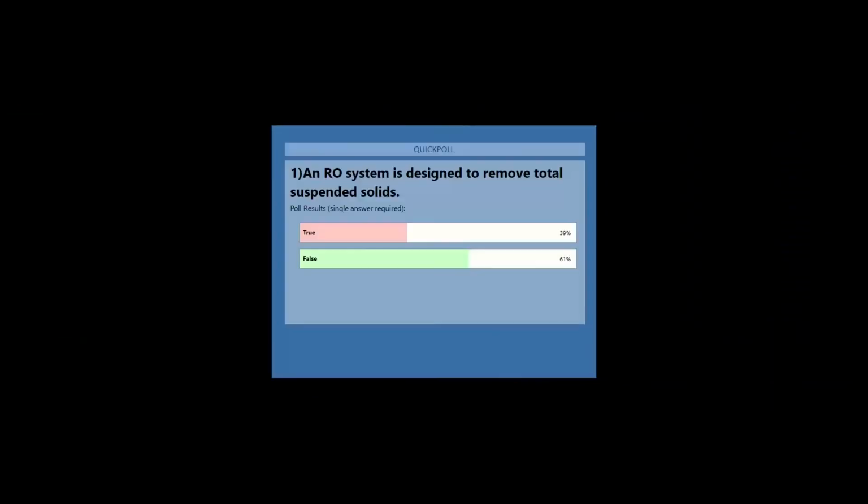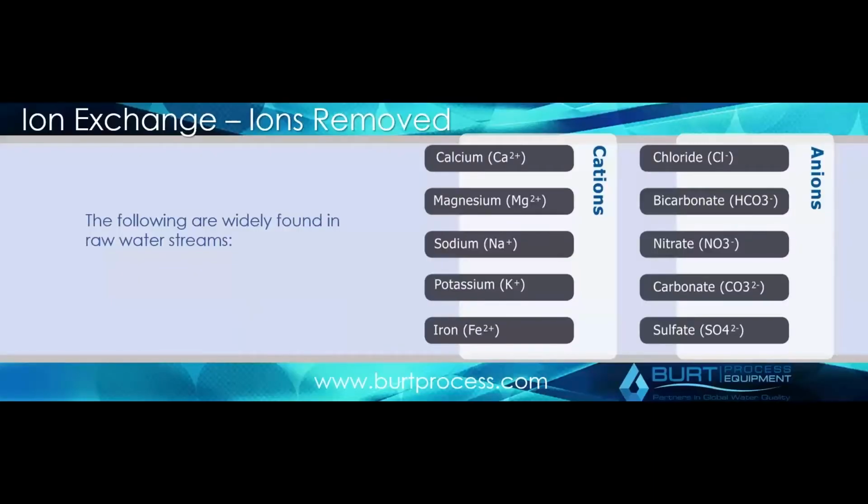Going back to ion exchange, you can see here there's a number of different ionic content involved in the system, which we just talked about: calcium, magnesium. So these are all on the RO projection. And again, you will take out 95 to 99% of these in the RO. What you're really doing with ion exchange is taking out that balance to a degree, moving these down into the ppb range, where you're going to get that much higher resistivity that a lot of high purity water systems require.